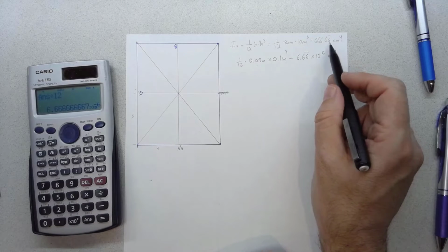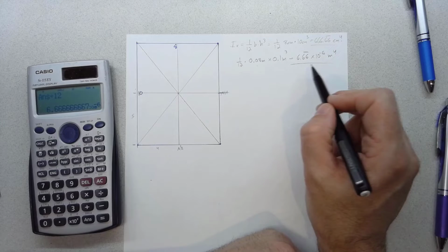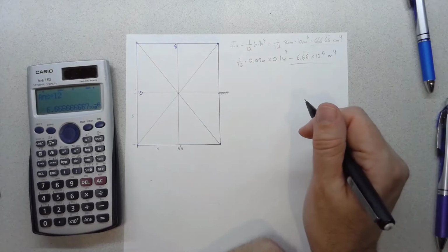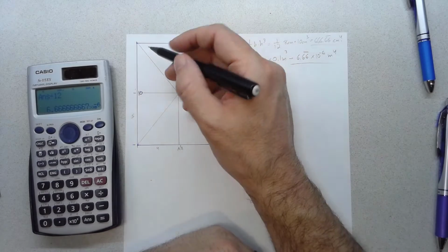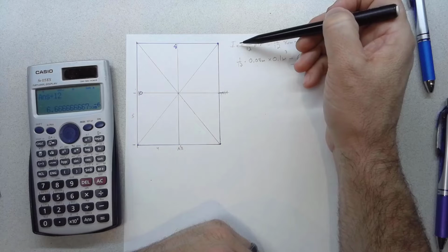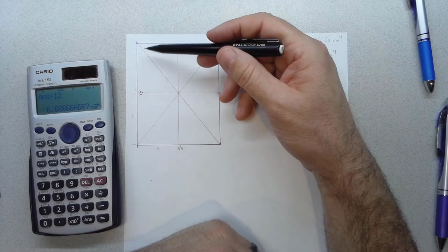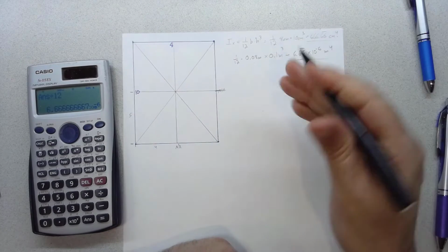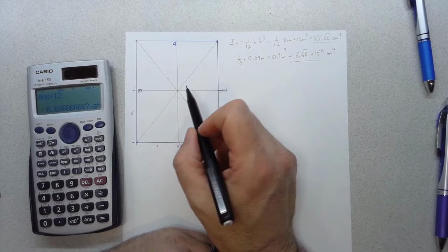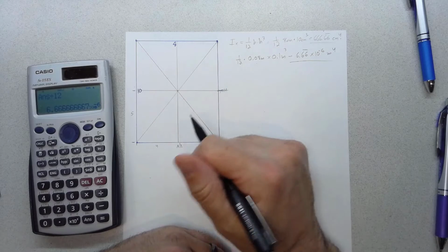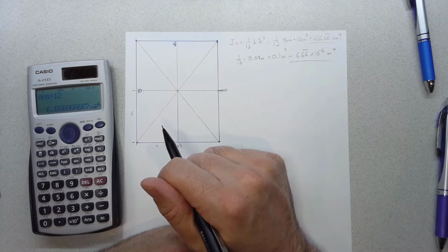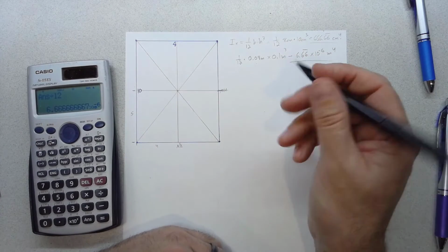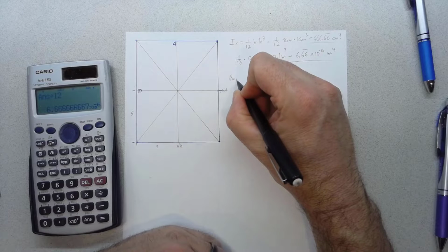So it's the same representation of I, it's just whether my units are in centimeters to the fourth or meters to the fourth. Okay, so that's finding the moment of inertia about a centroidal axis. When we start looking at composite shapes, I may need to know it about a different axis. And before we even get into composite shapes, let's look at it about a different axis for this one single shape. So that's when we use the parallel axis theorem.